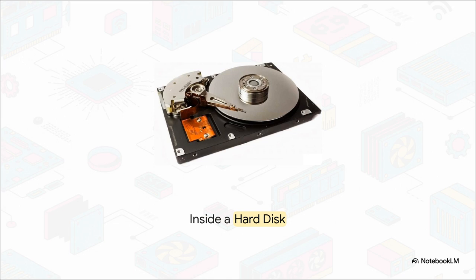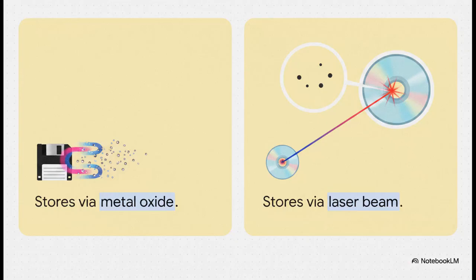This is an exposed hard disk drive, and honestly, it is a masterpiece of physical mechanics. What you're looking at is a platter covered in metal oxide, spinning at an absolutely incredible 7,200 revolutions per minute. That tiny electromagnetic read-write head on the arm interacts with the platter to perform operations. And the data isn't just thrown on there randomly. No, it is meticulously organized into concentric circles called tracks, divided into sectors, and aligned perfectly across multiple platters into cylinders.